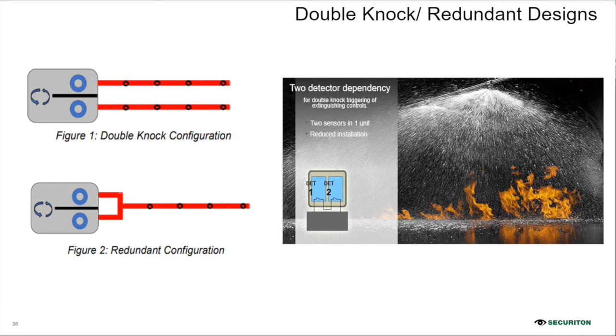Once the more sensitive point detects the smoke, it will give the programmed signals. It gives you hooter signals, buzzer, or any kind of programming which you have already done with this system. And when the second tube network detects the smoke, it will trigger the extinguishing system. So the system will actuate only when both detectors are in alarm. So this is the benefit.